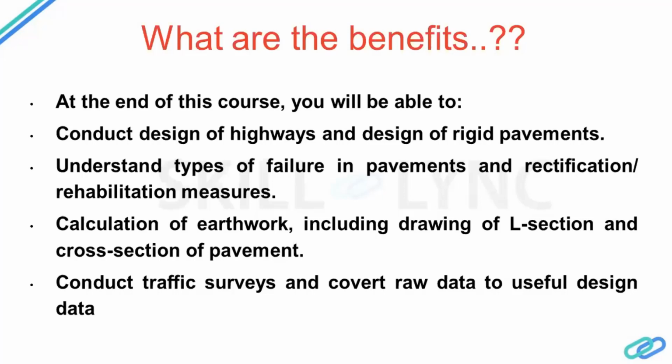And when you're designing a new pavement, obviously you don't have the traffic data for that. So what we do is we find a similar pavement and conduct traffic analysis on that road. So this is what, at the end of the course, I believe you will be able to understand.